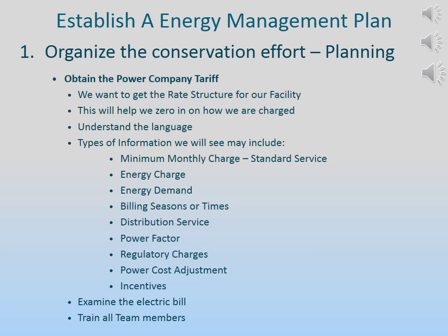One incentive used by one utility in Southern Maryland is to request that they shed load by using their plant's standby power. If they can switch over to standby power within 5 minutes of receiving notification and maintain it for the duration of the request, they receive a significant payback for that month. The only thing they have to worry about is having someone there to start the generator, or having a system that will allow them to start the generator remotely. Nowadays, with PLCs and SCADA, this can be done remotely.